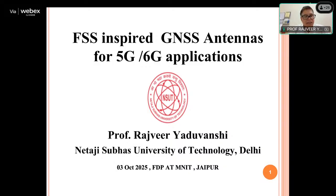One is the FSS structure designed to act as an absorber. Second, the same structure may look like it is acting as an antenna, but there is a change in wavelength. Generally speaking, an FSS structure designed for an antenna must be specific to the lambda by 2 wavelength, and an FSS structure designed to act as an absorber is generally lambda by 4.